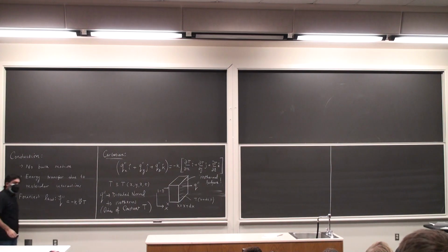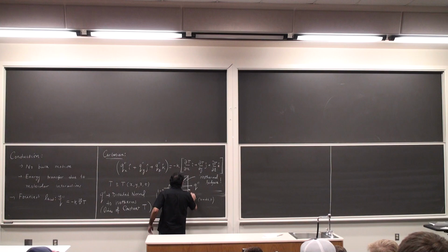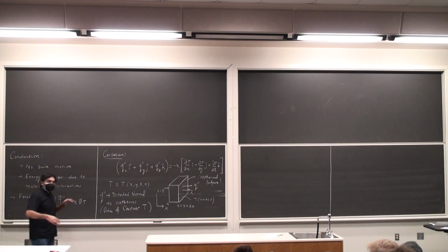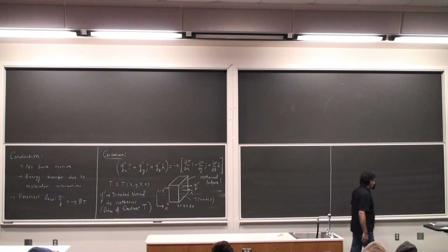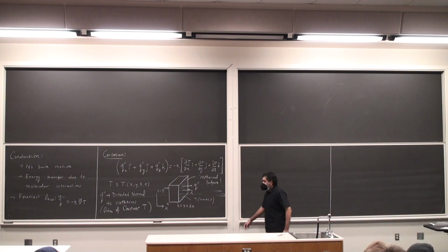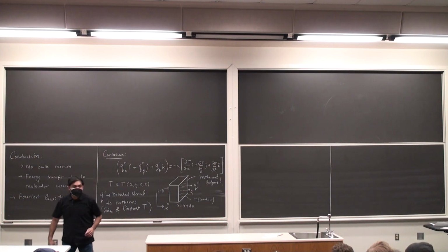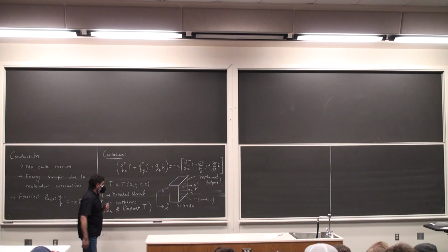And if you want, you can draw a normal here. n hat is the normal, and the direction of q double prime is along n hat. Alright, so not to belabor this point, but we've seen this before. What do we want to do in conduction? What's new? Of course, we can't prove Fourier's law. We can only prove it experimentally. That's no good. We're going to take it as a matter of faith, based on repeated observations without any exceptions.